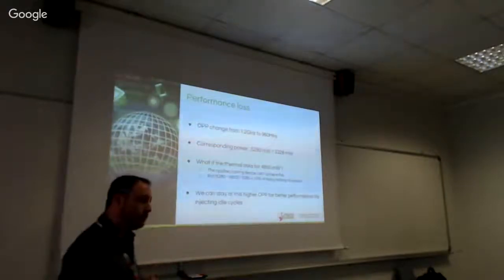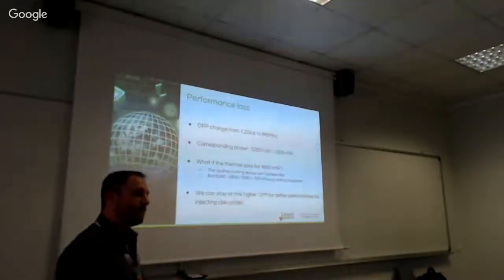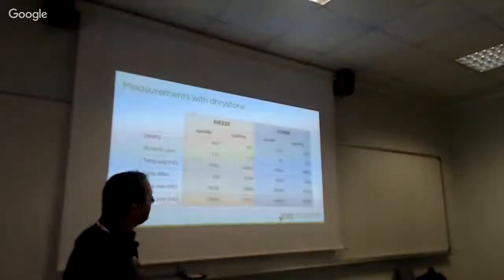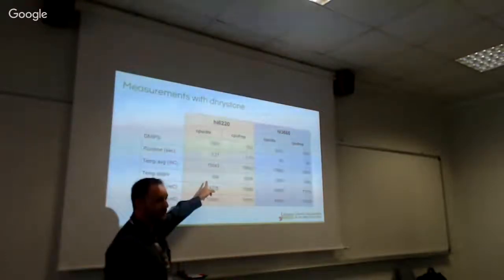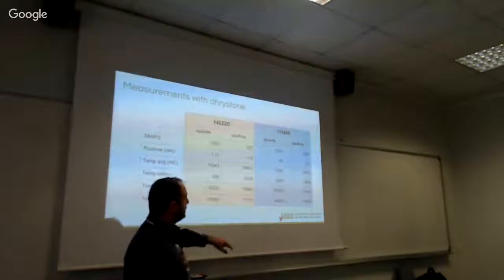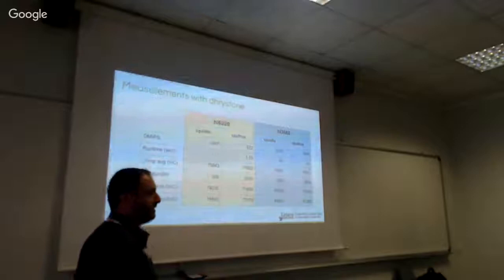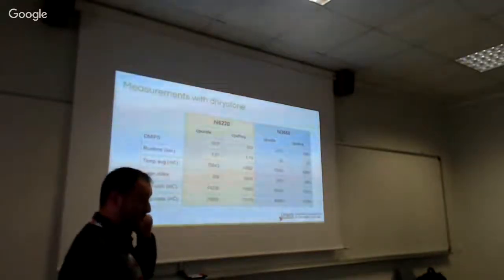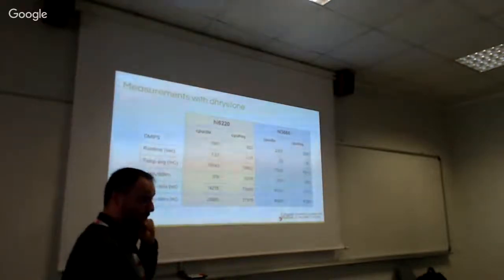Yeah, and I think they're far more consistent, and I showed in a table earlier as well. Can you go back a few slides? Where you had the table. The standard deviation of the temperature with the injection is much lower than cpufreq. Yeah. And that's again because you're using the wrong governor. Yeah, the governor plays a role. Because just modulating means if you do have two OPPs and you want to be in between, if you just modulate your frequency so you alternate between the two OPPs, on average you should get a better result.